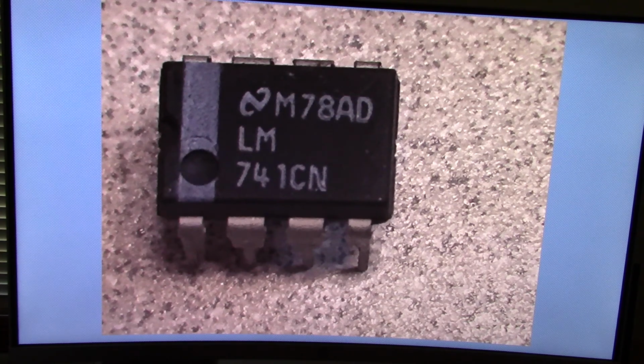And that's the actual chip. And here's that notch that I talked about. Well, the notch is here. The dot is here. And that's how I can tell which is pin number 1. Because for all practical purposes, you could take this notch and turn it around to here. That wouldn't tell you which is pin 1 then. So the notch and the dot will tell me which is pin number 1.